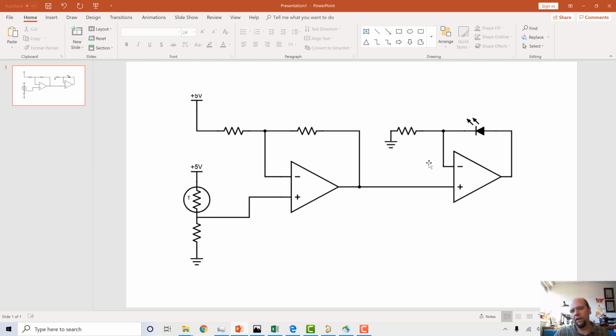And then this feeds into a voltage to current converter, where the voltage to current conversion is the ratio of this voltage applied to the pin divided by the resistance of this resistor. So essentially, to choose the voltage to current gain, we're going to change this resistor value. For this design, the values here don't matter. That's not the part that I care about. Ultimately, for your design, you're going to want to put your actual resistor values. I'm just going to build this thing with generic resistors and not worry about the calculations right now.